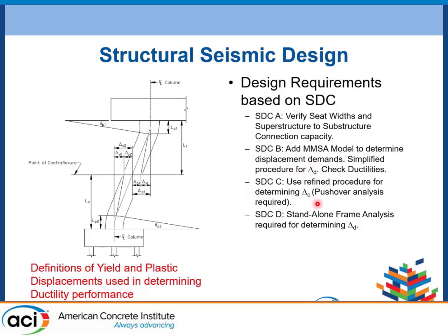Once we get to SDC C, we actually have to use analytical modeling techniques to do both sides of that equation. And then at D, we also have to consider each frame on its own as opposed to allowing the entire structure. And here is just some of the definitions I mentioned before about relative locations of the bridge elements, as well as some of the displacements.